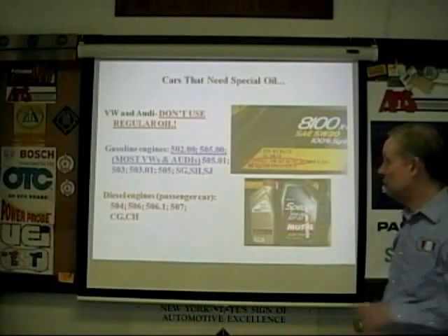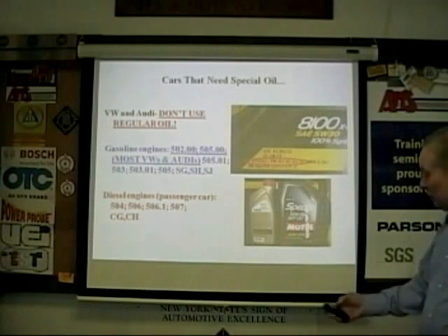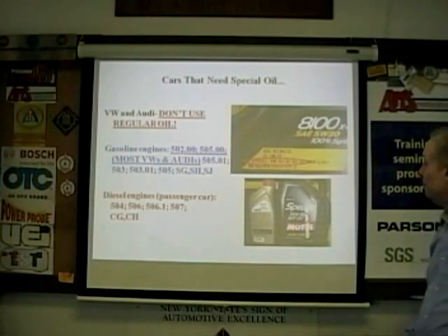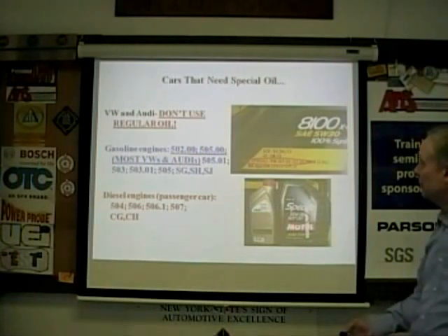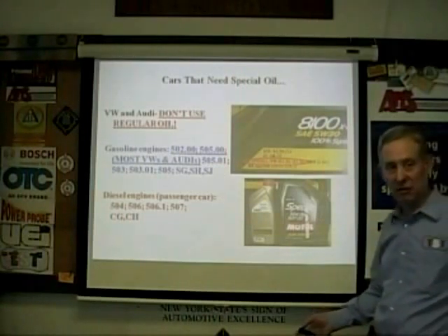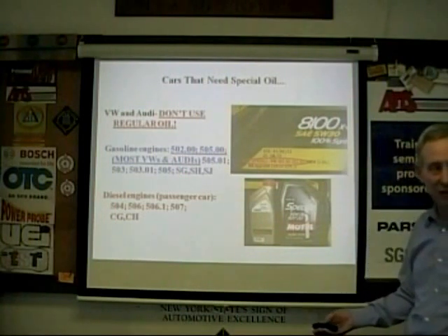So Volkswagen out here says you can't use a regular oil at all. Cannot use a regular oil. It has to meet their specifications. Then does that mean that they only use synthetic in those? They only use synthetic in those. Those are all synthetic oils in VW now. From what year? That's a good question. It's a long time now. It's in the mid-90s on. Okay. Early 90s on, I think. Been a long time. Pretty much anything you're going to see.